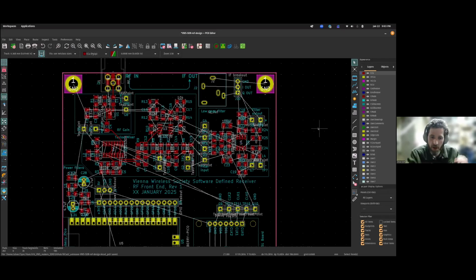This is an easy way to fill those two inner layers of the PCB and all the empty space in the top layer and the bottom layer with copper, and then we'll put some vias in to tie it all together so we have nice solid ground in the next step.